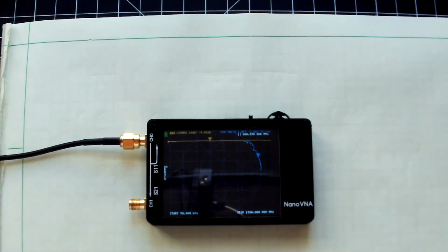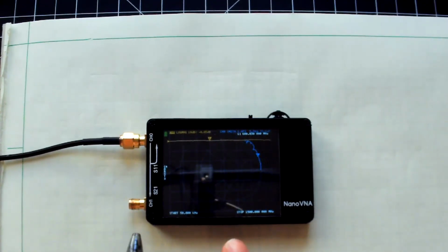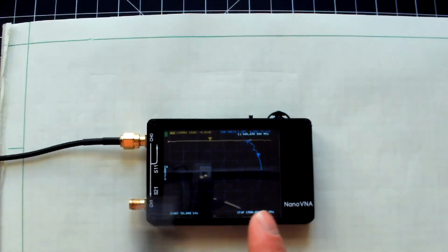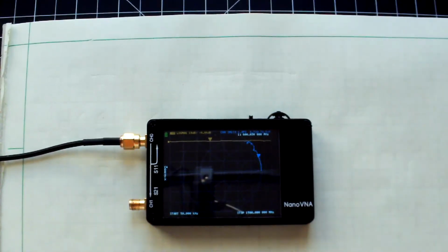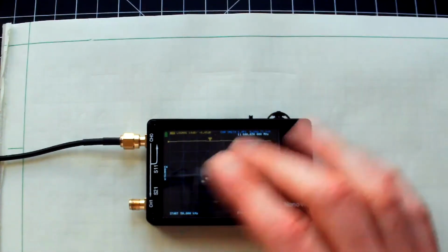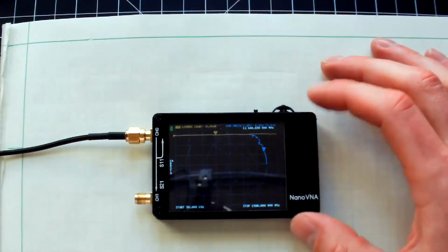What would be really neat is to chop it up into 4 blocks. So the first block would be 1 to say 250 megahertz and do 101 samples, and then go 250 to 500 and do another 101 samples, and so on. Like I said, I know that can be done. Steve Blair put together some code for that. I just haven't done that. And again, you don't necessarily need that resolution because, as you saw, you got pretty decent results from that TDR sweep anyway.